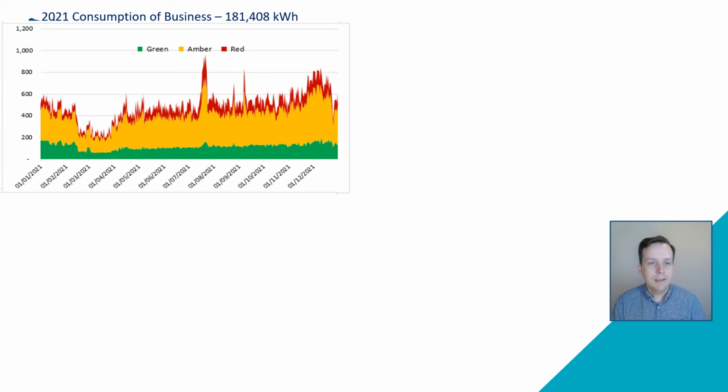But that's where you would first look at, well, has something been left on that could be switched off overnight? Some of the fridges, certainly the drinks coolers, could be switched off overnight without having too great an impact on the coldness of the beverage. So that's where you start looking for energy efficiency with half-hourly data.